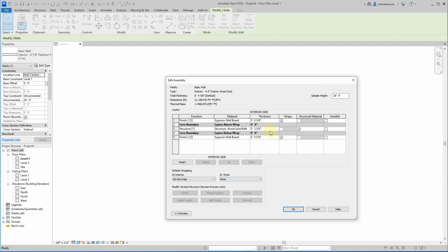Because it's an interior wall, oh, I should have done 4-inch on the other one, or 6-inch nominal. This should be 4-inch. So, oops, 3.5 inches. And then I'm going to call this 3/8 and 3/8. So we have a somewhat thinner wall now. Actually, let's do 1/2 inch.